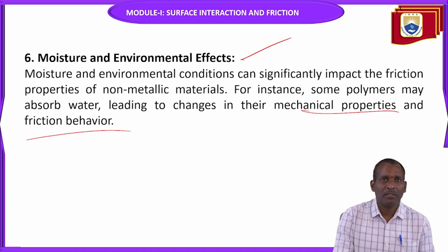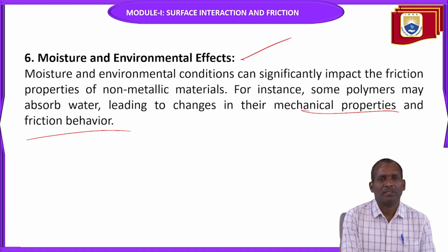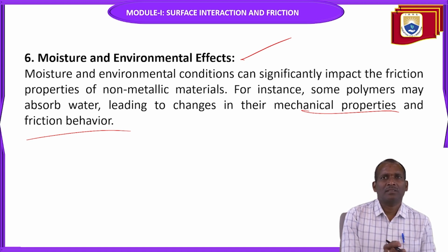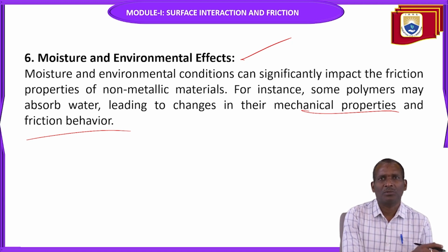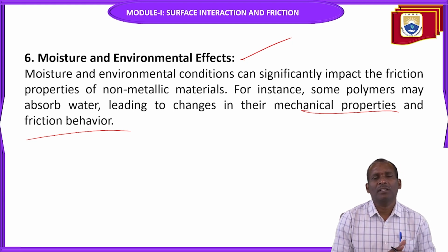So polymers may absorb water. Due to this absorption of water, there are changes in their mechanical properties. Many mechanical properties are there: strength, hardness, creep, ductility, malleability. So it leads to changes in these mechanical properties, and automatically the friction behavior also will be changed.